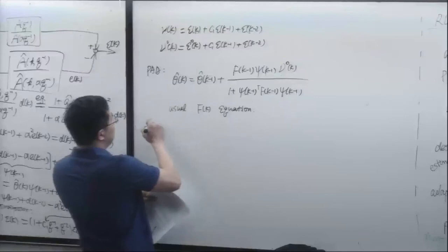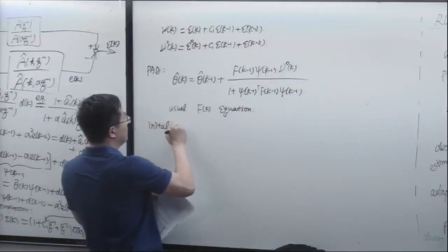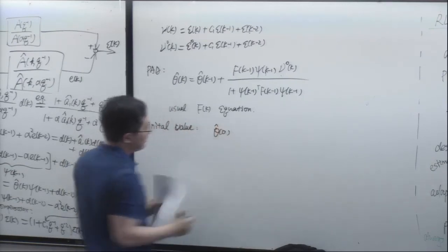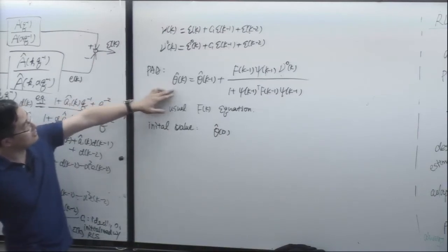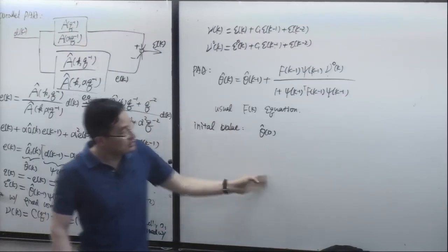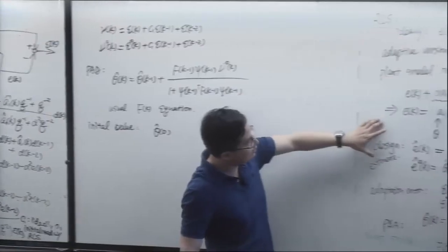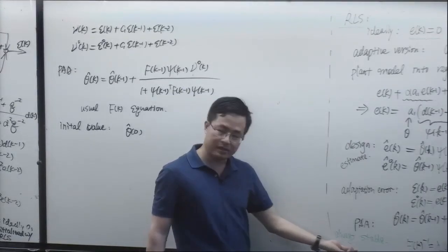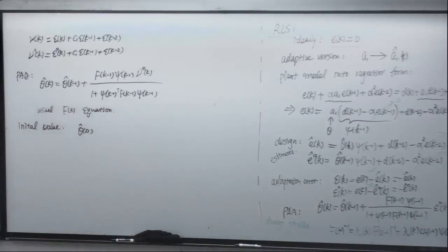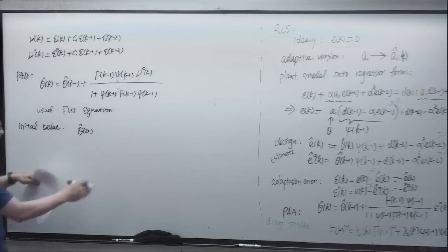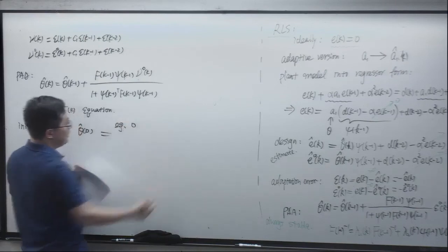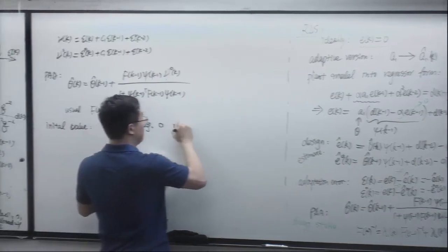Now, let's talk about one thing. We said we need to initialize. This covers everything once your algorithm has been running. We need to initialize it somehow. For recursive least squares, usually it's pretty tolerable. The algorithm will always be stable, so it may not converge 100% to the absolute value, but it's going to be reasonable even if you initialize it with 0 in recursive least squares.